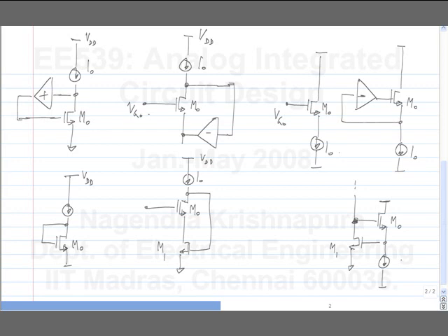If the drain was? No, it will not be the same as the third case because whatever it is, this will also have feedback to the source. The question was if the gain of amplifier is -1, is the circuit exactly the same as this? No, this circuit is exactly the same as this if the gain of the amplifier is 0, right? Because if the gain of amplifier is 0, then the gate voltage is fixed. So only then will that be the same. So there is always feedback to the source. This amplifier represents the amount of feedback to the gate.